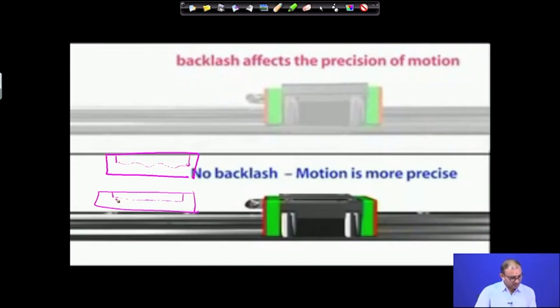You will not get a flat bottom surface on the machined surface, because your workpiece is moving in a wavy direction, and because of that you are not getting a precise movement of the cutting tool either. That is what is going to happen because of this backlash error.